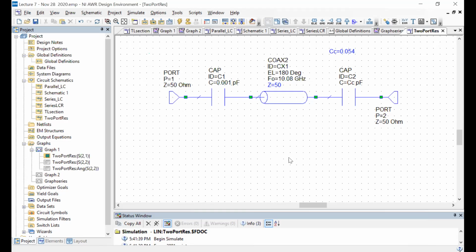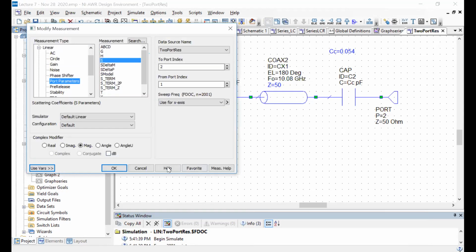Well, okay. So, a couple of things there. All these calculations which we are doing right now in terms of the scattering matrix are all relative measurements. And this is a linear system, so it actually doesn't matter. The actual power doesn't matter. Whatever power you put in, everything will just scale linearly with that quantity. Now, if you're talking about what is the power coming out of port 2 relative to what we have put in, that is of course related to the mod square of this quantity.